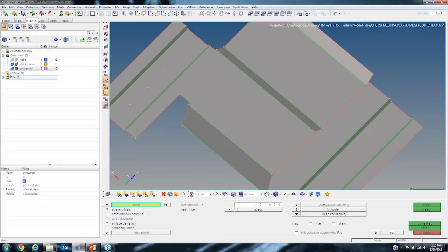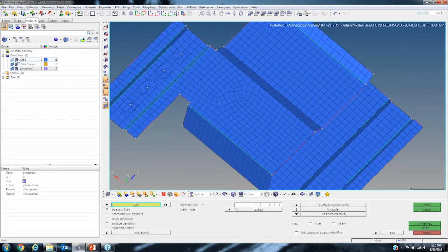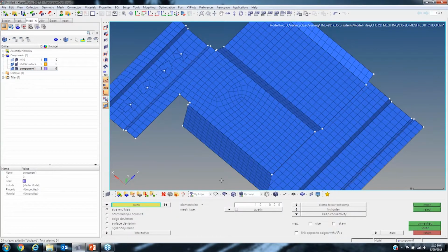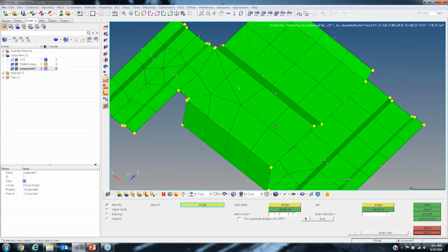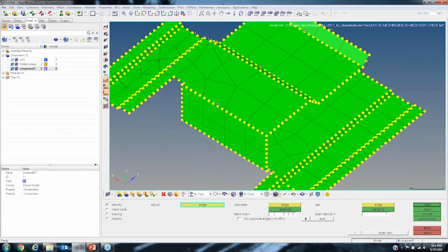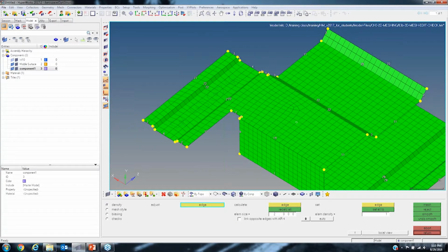And my mesh just disappeared here, so it's probably set to this blue one here. So you can see how I didn't quite notice that this one was set as the current component. So what I ended up needing to do is change this to the current component again, and then just remesh the whole thing again. So select all of the displayed surfaces, click mesh, and set this value to 2, recalculate all, and remesh. Okay, so we're back to where we started here.